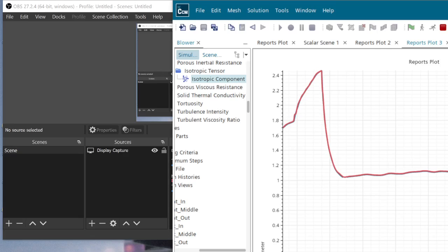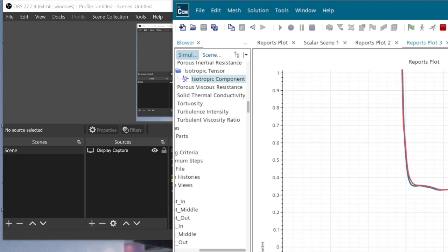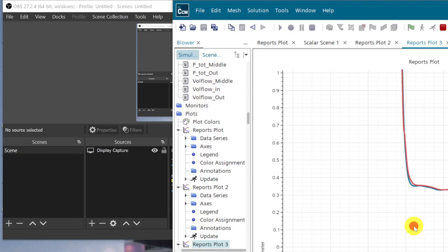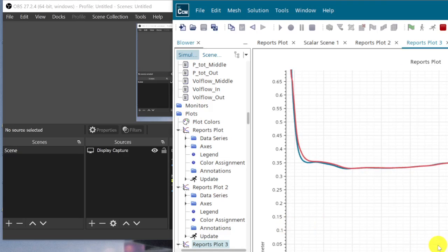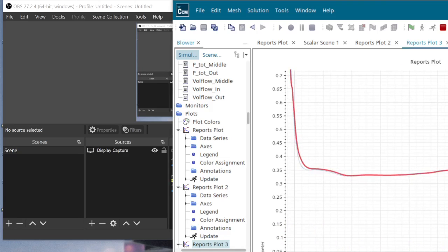I'm just going to keep on adding zeros until it gets really small. Okay, like 10,000 looks like it might be enough to basically entirely choke this fan at 1,500 RPM. It's still kind of figuring out what's going on, but that's a really small number. So your bookends are probably 0 and about 10,000. Maybe 15 or 20,000 because you're operating at a higher RPM, but something in that general neighborhood. Again, we want something that's really, really close.